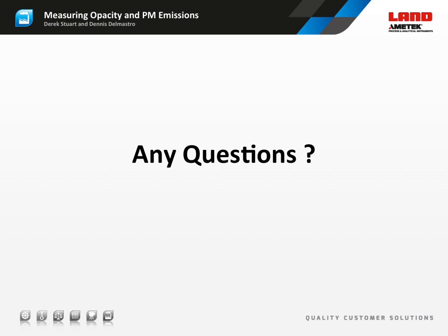And Derek, this questioner would like to know, why does my opacity monitor sometimes give negative readings? Like any measuring device, an opacity monitor has a specified uncertainty. Some of the uncertainty factors, such as lens contamination, will always give a positive offset. Other factors, like installation path length or the electronic noise, can give a positive or a negative offset.